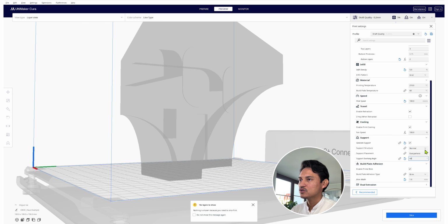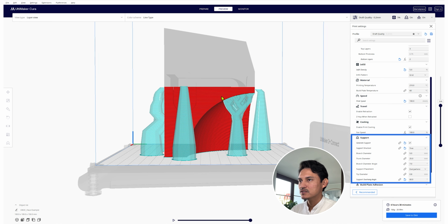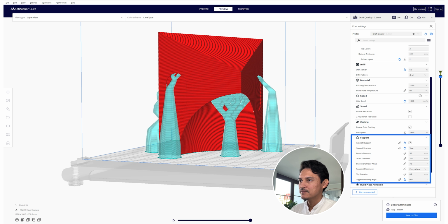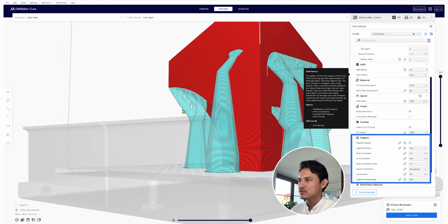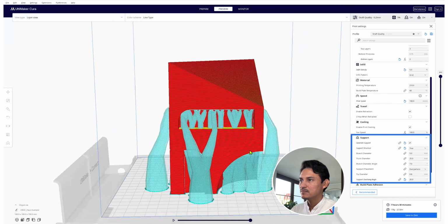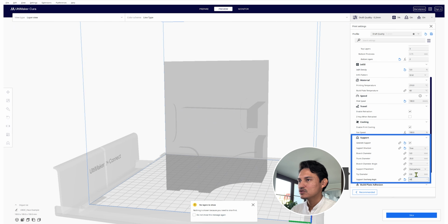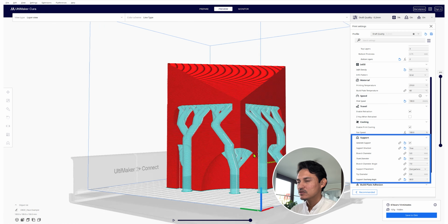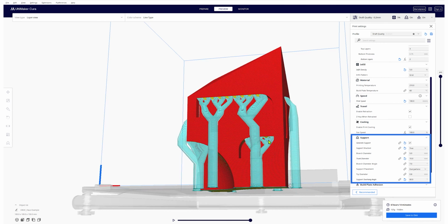You can also choose tree-like support structures. And also here, adjust the shapes of the branches of the trees and the overhang angle. Always check that the geometries of the trees look logical enough to support whatever they have to. PLA is strong, but I would suggest trunks that begin with at least 10 mm diameter, so the supports are robust enough.